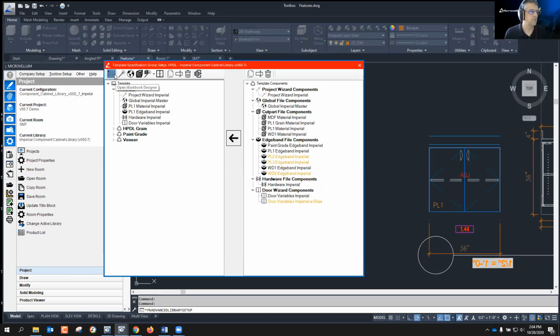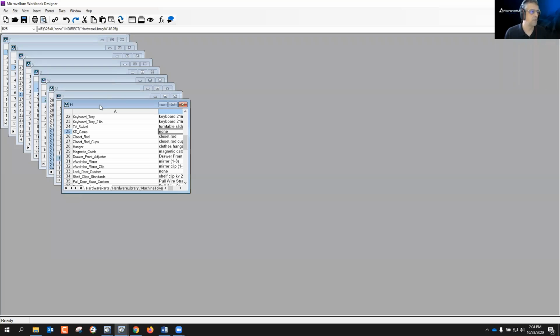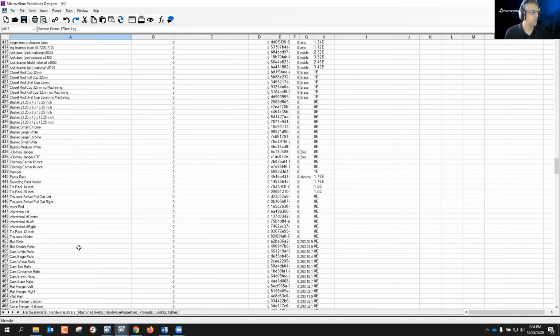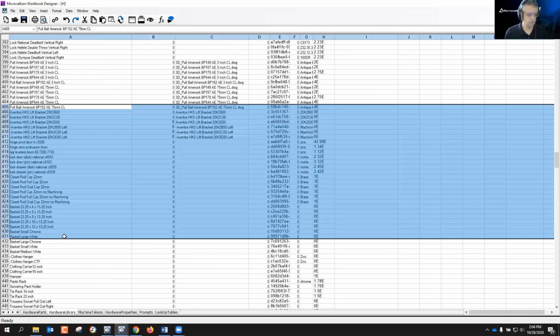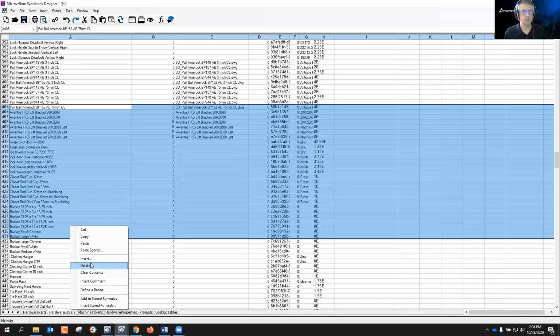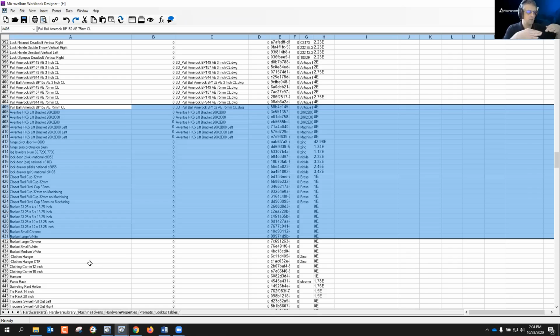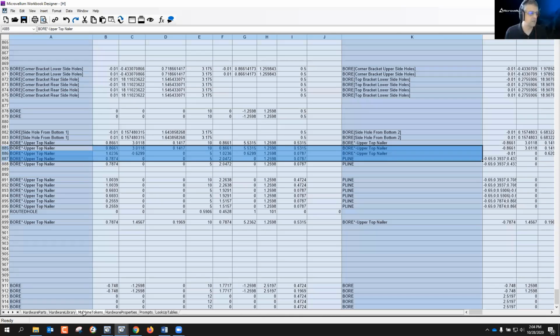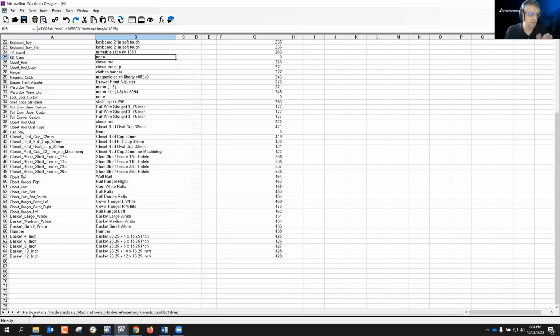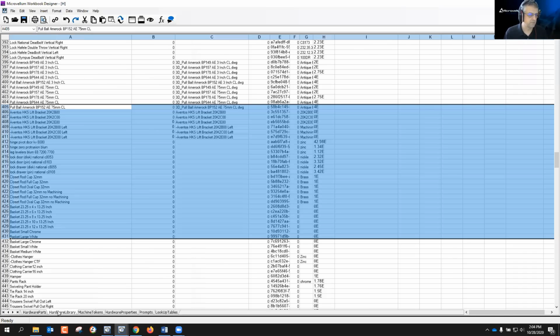And that's really important because you do not want to manually remove these. I'll tell you why. You do not want to come in here and say, oh, I'm just going to delete. Don't do that. You want Microvellum to do it. The reason is when that gets shifted up, you also have to simultaneously shift up the machine tokens. And there's other things going on in here that are referring to rows. These are your pointers. Let Microvellum do it. Some things in data you can do manually, not this. And so that's what that button does.